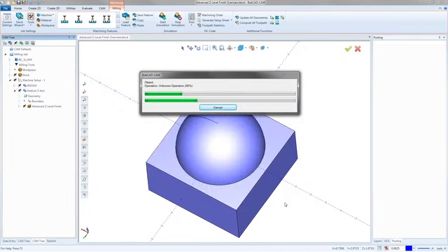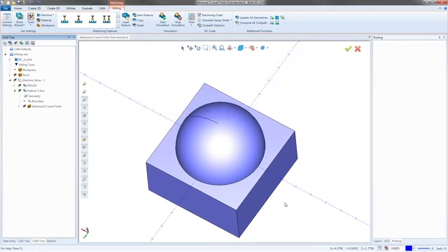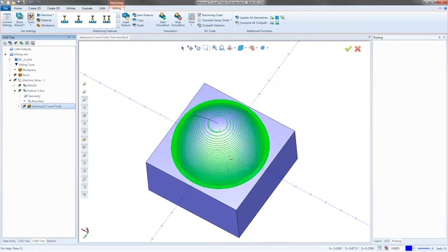And so if you have access to the Pro toolpaths and you want to do a spiral toolpath, use the equidistant. The equidistant is going to give you one of the most beautiful spirals you've seen. The only downfall to it is no arc moves. So there's really not a good or bad way of doing it that's going to be consistent. In that case, it comes down to how much room your machine has. If it can fit all of it, then you're fine. But if it can't, there it is.